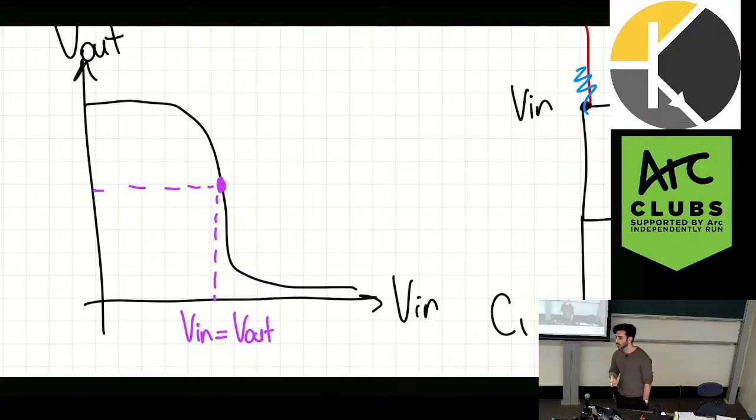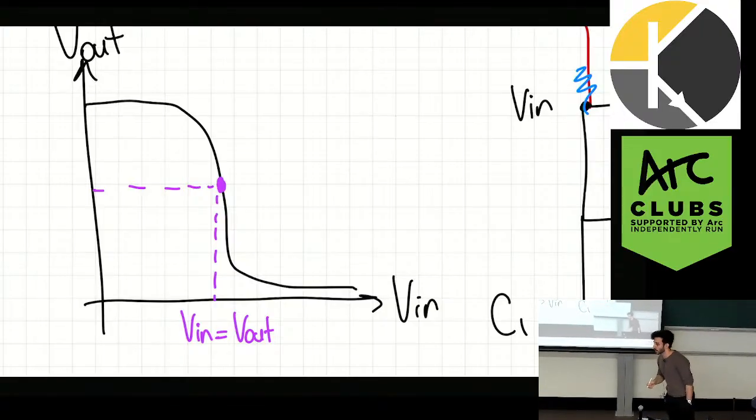So you basically stabilize that point? Stabilize what, sorry? That point right there. In the middle? Yeah, essentially, that's the default biasing point of the thing. So it's an inverter, it's digital logic, but we're using it like a linear amplifier, right? Just to get this started, okay?